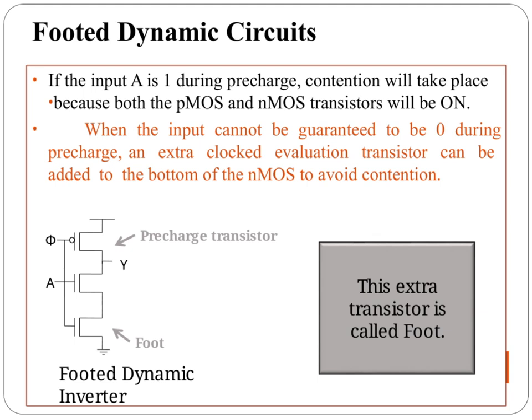This additional transistor is known as the foot. By adding the foot transistor, we effectively isolate the evaluation network during precharge, eliminating contention and improving circuit reliability. This concept is illustrated here with a footed dynamic inverter, where the foot transistor controls the connection to ground during different clock phases, ensuring proper operation.